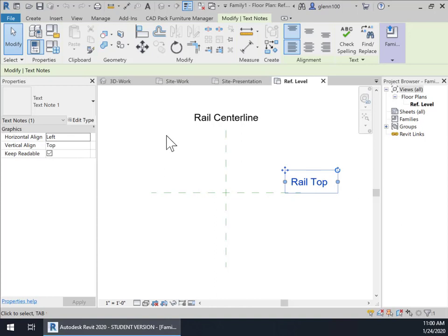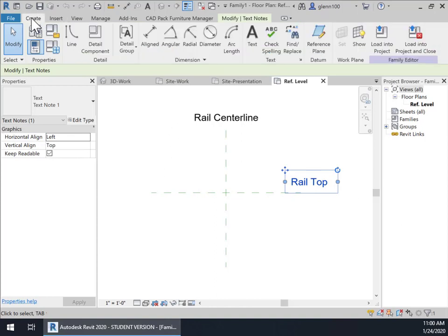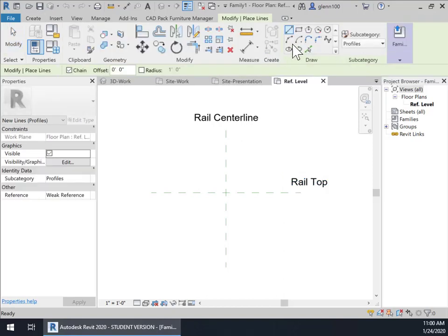And to do that, it's pretty simple. I'm going to create a line and then a rectilinear line, and I want the top of the rail to be the top of the curb. And I know that curbs in the States, or in Lubbock at least, are usually 6 inches by 6 inches. And so I'm going to just put that there.